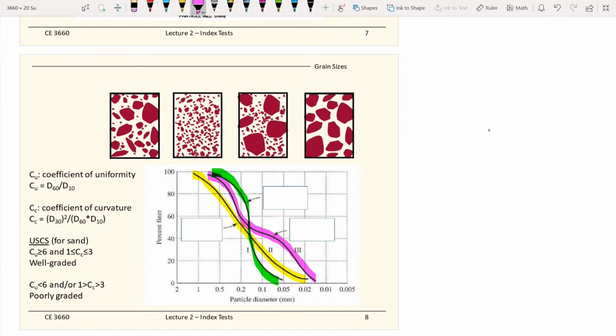Because if you're an engineer, what you get on your desk or in your report is not a soil sample but a soil report. In any phase of any civil engineering project, there has to be a geotechnical report, or people call it the soil report, to represent on the project site, for your foundations, what type of soils you need to deal with.